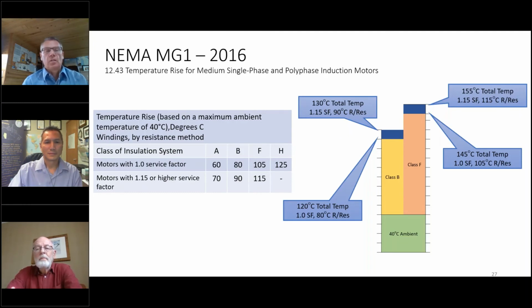And even in the coupled condition, if you're seeing you're pulling 50 amps, maybe there's something else there. It's one of the ways to look at it. Obviously alignment, things like that. But like I said, current is proportional to torque, so you can look at that. I'm not sure if that helps.